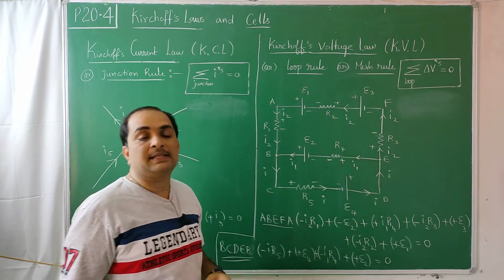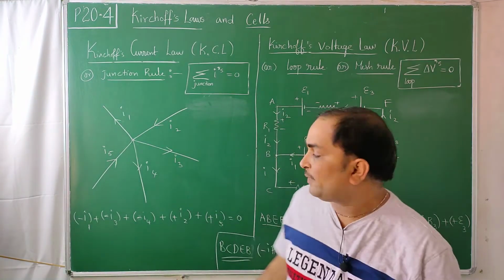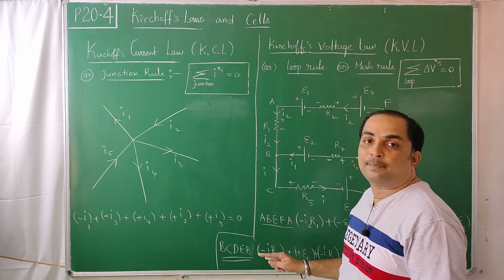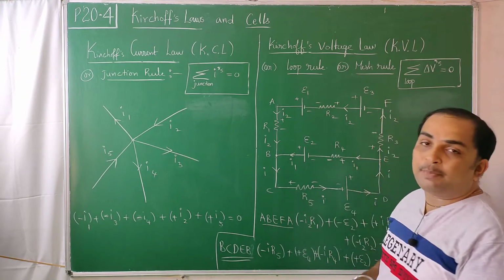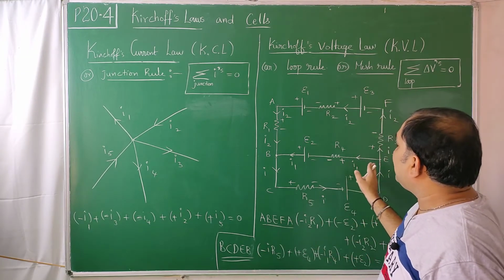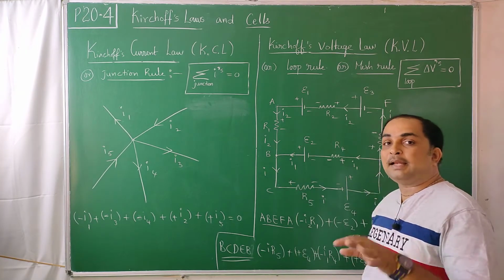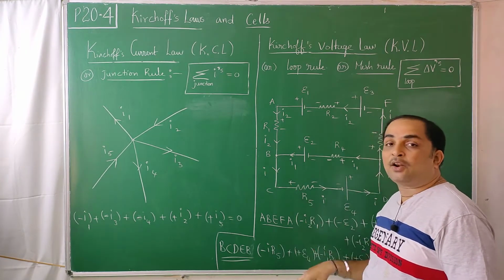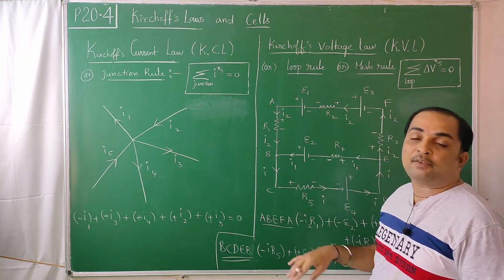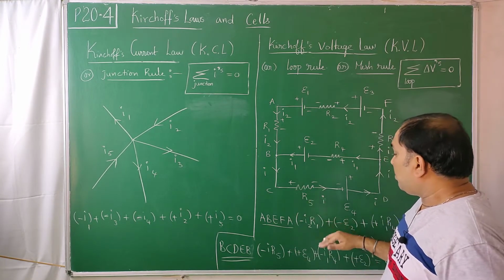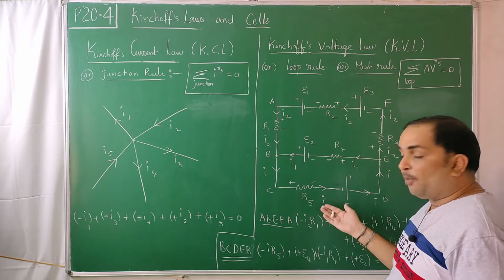If you made any mistake in the sign when you are solving these two equations, for example, you have to assign current to the right side but you assigned it to the left side, which is wrong, then both your equations are wrong in the sense of direction. What you have to get here, you will get the opposite.